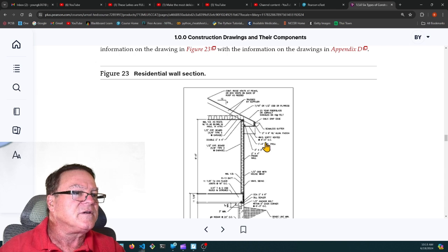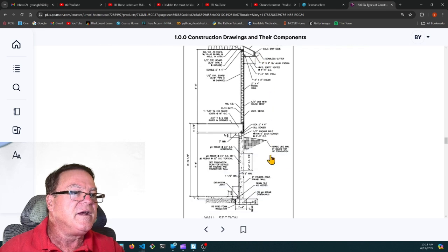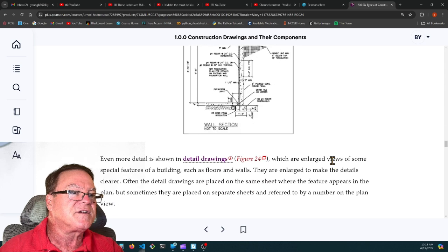It almost, well, and then there's a rain gutter on the outside. All right, so this is showing, and then look, here's the ground. There's a cross hatching, so this is the earth. This is the bottom floor. And they actually have a basement underneath the ground. They're showing that here. Here's a poured concrete wall and slab on a footer. And there's the section underneath.